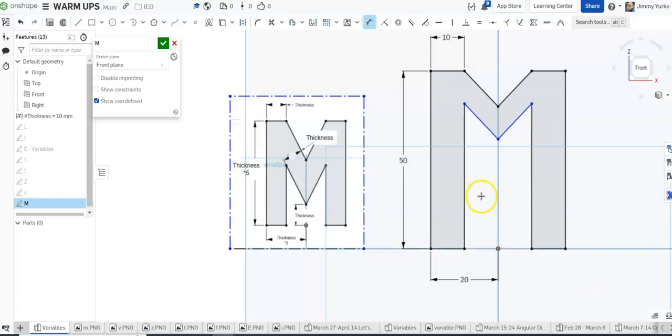And we've got a thickness measurement here, so measurement from this line to this line. And if you have that correct, notice that that is a linear dimension, it's a straight line, so it's just asking for a number. If yours asks for an angle, then you need to make this line and this line parallel.